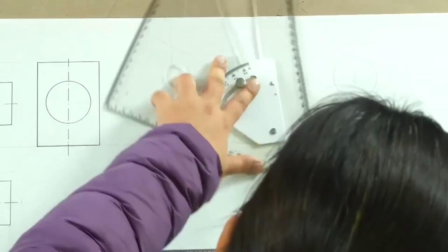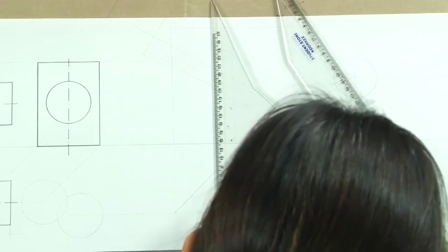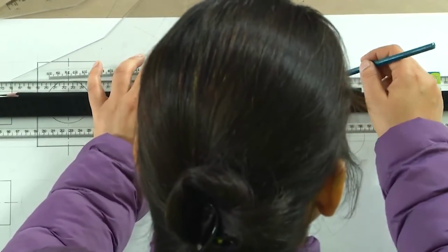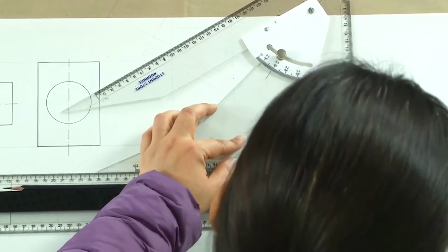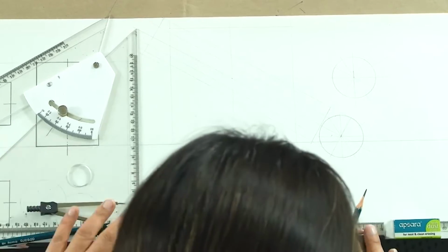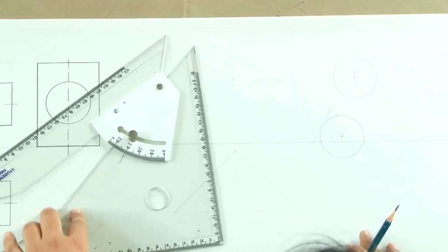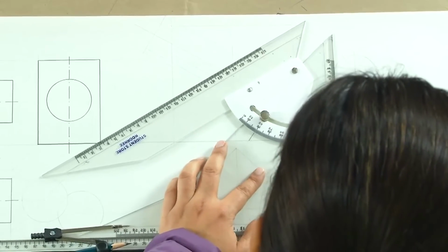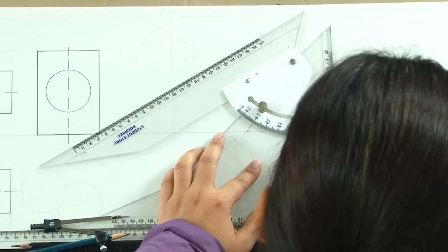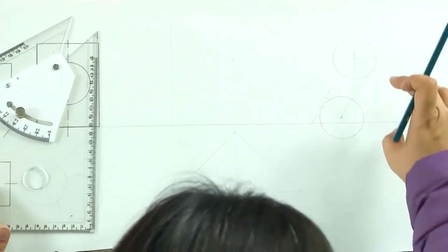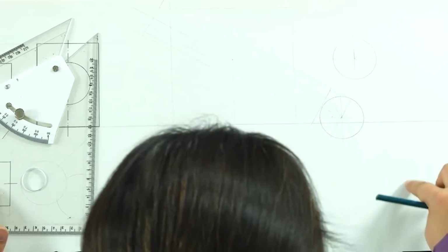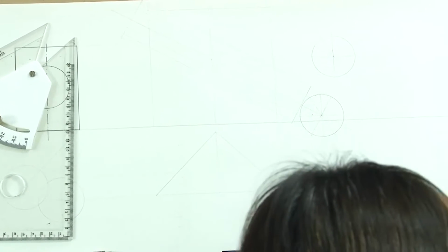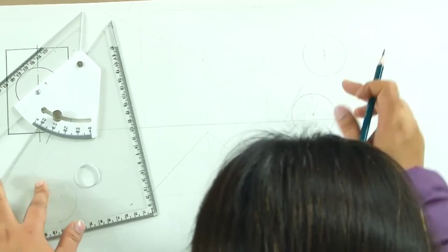Now, why are we required to draw these 12 points? It is to get their horizontal projections in the plan. So, if we bring it back here, we will be seeing the horizontal projection, and if we take it from the top here, we will be seeing its horizontal projections. So, if we see it from the top, we have another circle here and the 12 projection points which are seen here. So, this is actually the side view, and if we get it again here, this is where all these points are going to come.